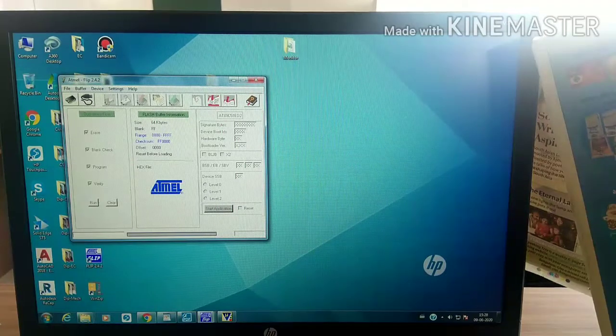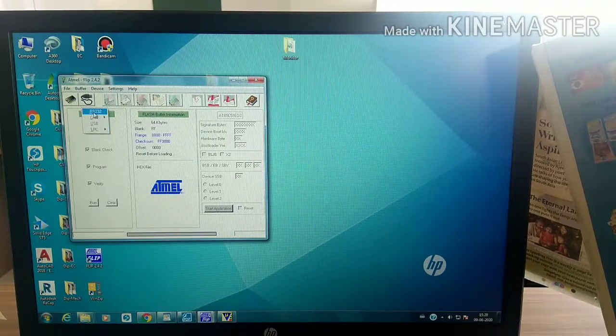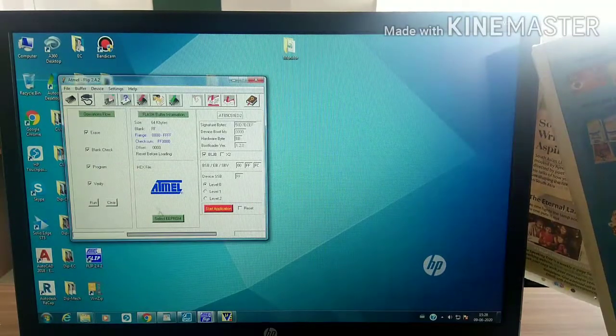For interfacing programs I need to use this second software. I need to make the connection. Here, set communication, click on the USB cable connection. Which one? We are using RS232. Next you can keep whatever is displayed as it is. Just connect, then all the options get enabled.